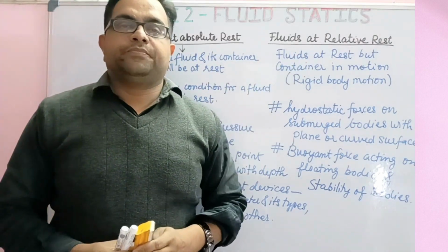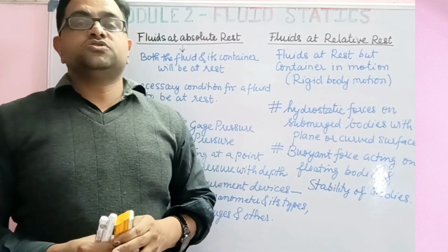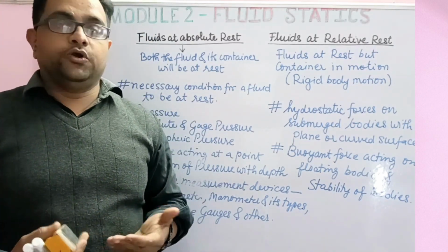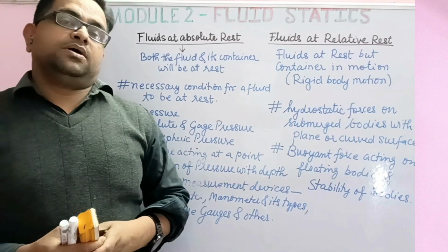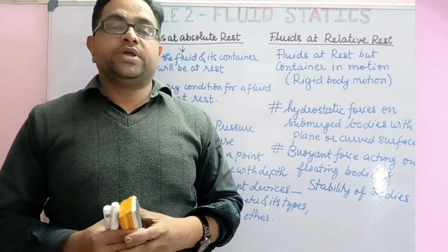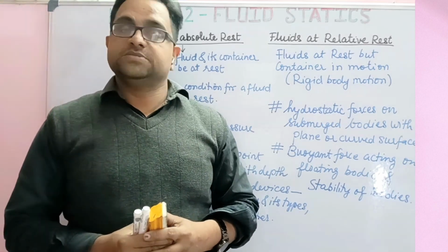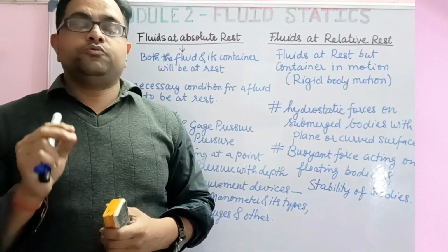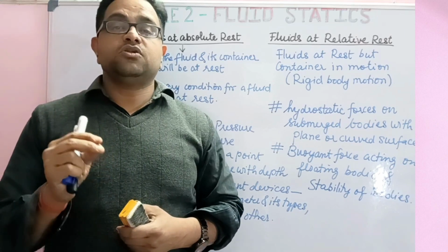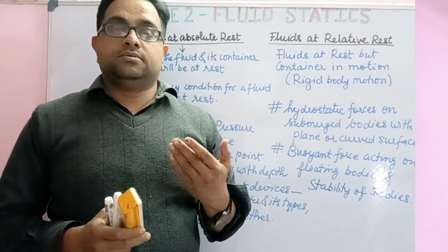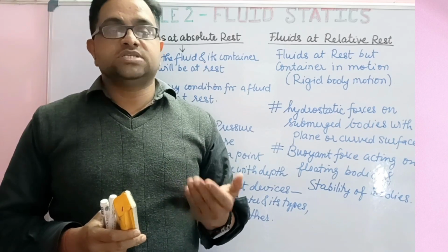Now, you may think of the various applications of fluid statics, or what are the various uses of fluid statics. So, let me discuss those. Using the principle of fluid statics, we can compute forces on submerged bodies, as well as we can locate the point of application of the forces on bodies such as, say, dams, ships, or submarines.